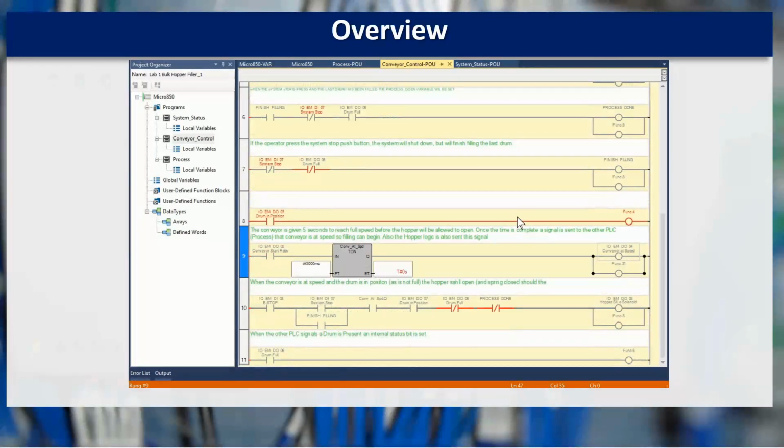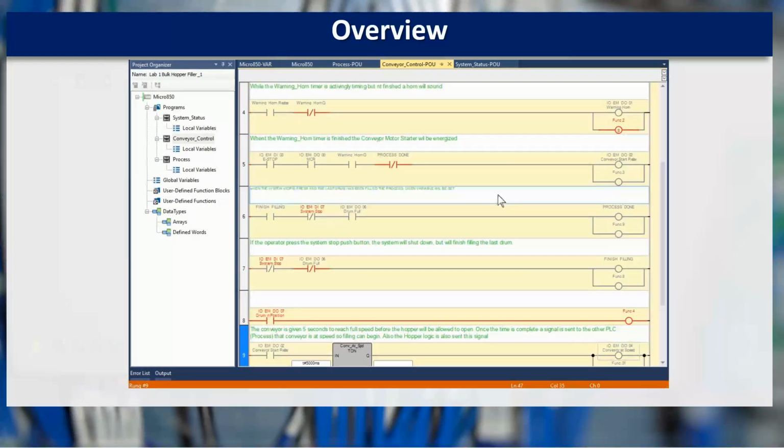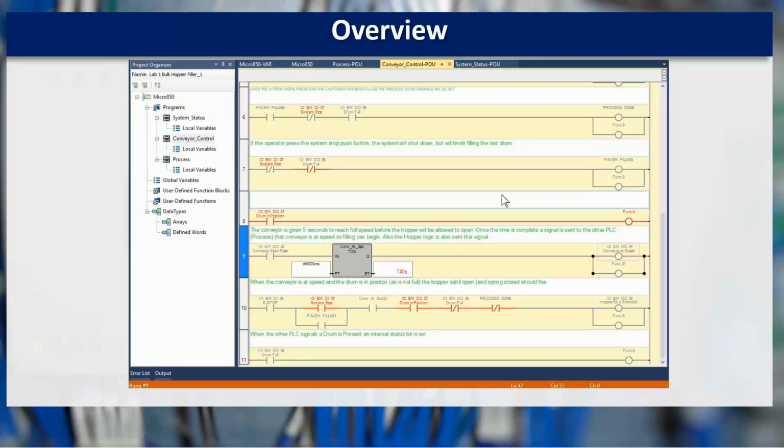The part of the overwriting of other parts can be a little tricky. It takes some time and some careful thought, and I did the same thing that quite a few did. I forgot a rung of logic to put some commentary on. Also, there was a requirement for a header rung, and quite a few missed that as well. But that's basically how that program was supposed to work. There was variations on a theme. Some of you came very, very close, but it's one of those ones that takes some careful thought and using some internal variables to help you to set an internal bit that you can then claim that the thing is done.